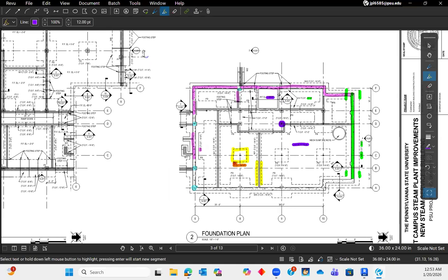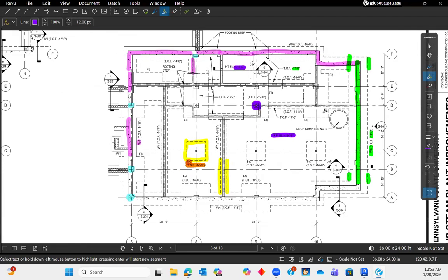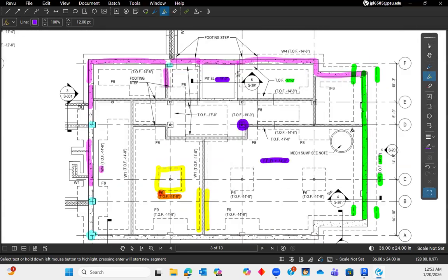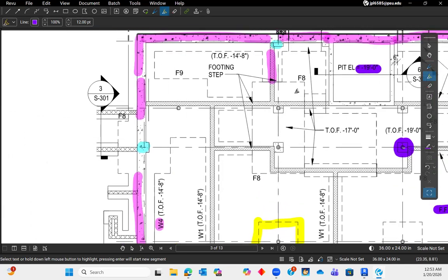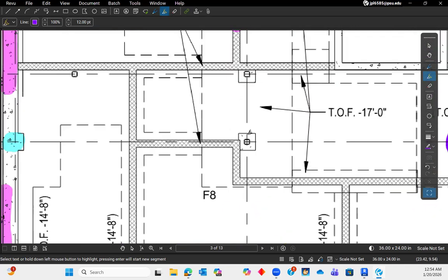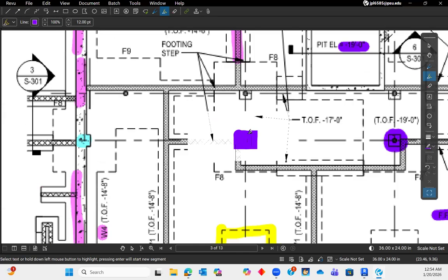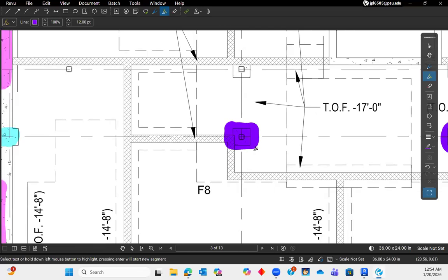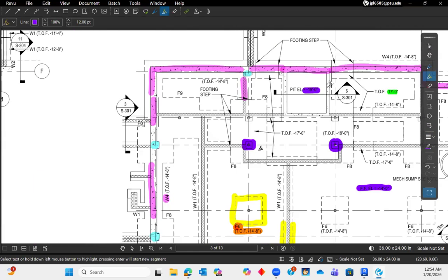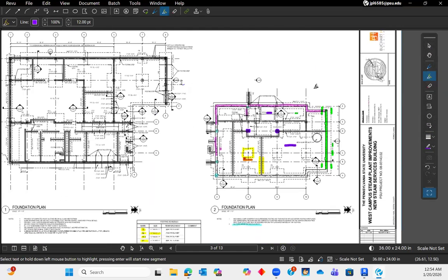I just wanted to pull up my old Revit project to show you what I was talking about. I wanted to clarify about the piers. This is another thing you are going to have to get used to. When reading these structural drawings, if you see the outline of the pier in the drawing, that means, like you can see the walls, it is going to start at the base of the footing and stretch all the way up to 8 inches below the floor above this foundation plan.